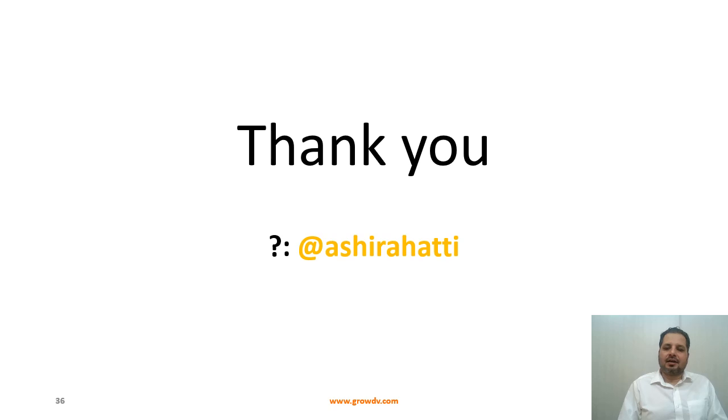That's the second part of it, how the process of randomization itself works for class-based randomization. So one is we have this object-based randomization, and second we have the procedural randomization. In the procedural randomization, in any task or function, if you want to do the randomization, how do you go about it? In that context, we saw the built-in standard package has the randomize method, and then we saw a bunch of system tasks or functions like urandom_range. We looked at how we can use those for doing quick randomization within the context of a task or function without actually having to use the full object-based three-step randomization.